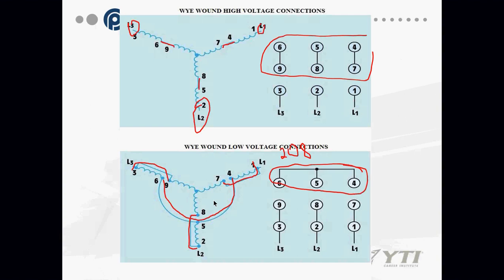When you go to the low voltage configuration, I now have two complete sets of windings that are in parallel to each other. So I could be increasing the strength of the motor by putting another set of windings in parallel using the lower voltages. Which is going to draw more amperage? The first configuration or the second configuration?